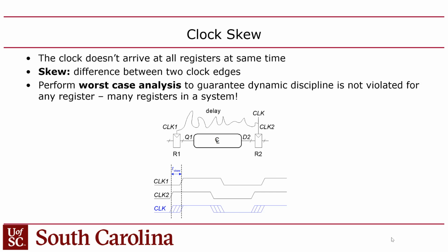Yes? Can you have, for example, some oscillator in the center, and then in equal parts, it will be the same delay, like equidistant from the center? Yeah, but it's still going to depend on where you are relative to the center, even if you did that. But generally, the way the clock works is it comes in, clocks are always generated with a crystal, they're piezoelectric. And then the piezoelectric oscillators are usually limited to about 250 megahertz. And then you might say, well, if that's the case, how do I have a 5 gigahertz CPU? Well, it comes on the chip, and then they are able to multiply the clock on the chip.